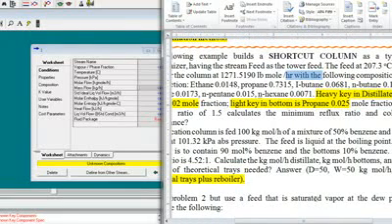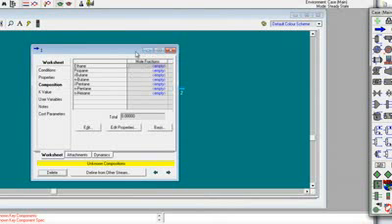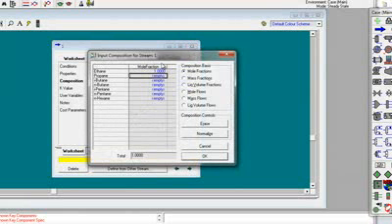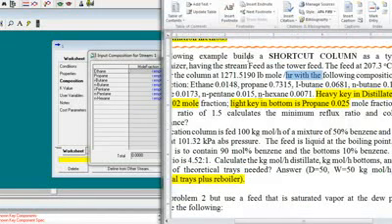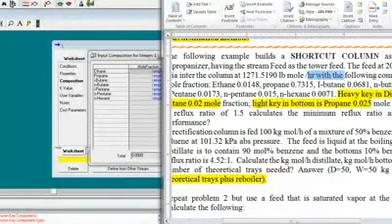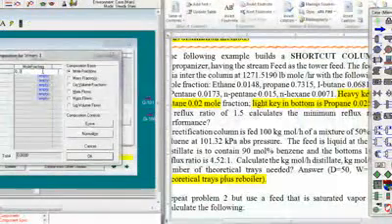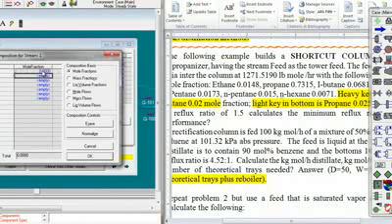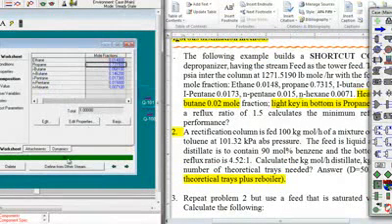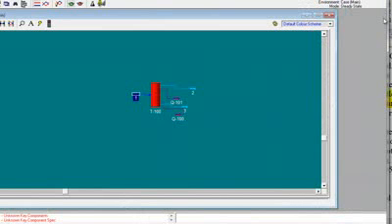And for the components, of course we add the composition of the feed, and it's here. You can press any number, for example, then you delete it. Now we choose the mole fraction. As we can see here, it's in mole fraction, so we add them slowly in mole fraction. We have 0.148, and you have to be sure that the total of all of the composition fractions should be equal to 1. Now press OK, and now it's ready. So we close it and we come here.